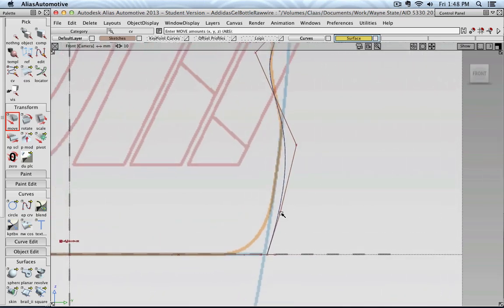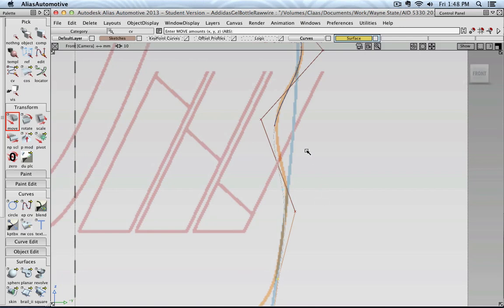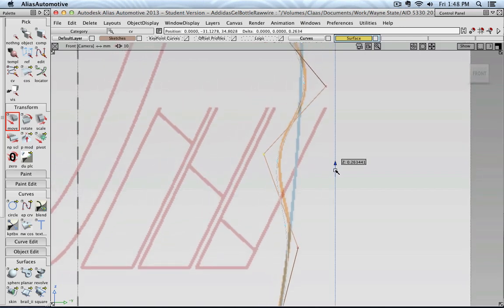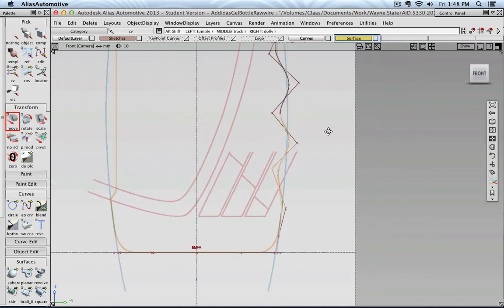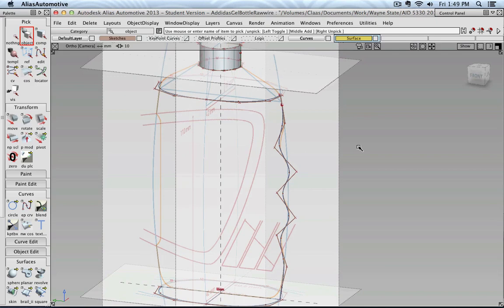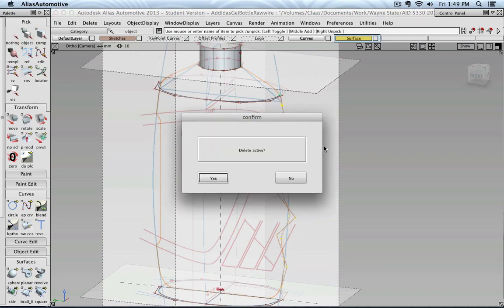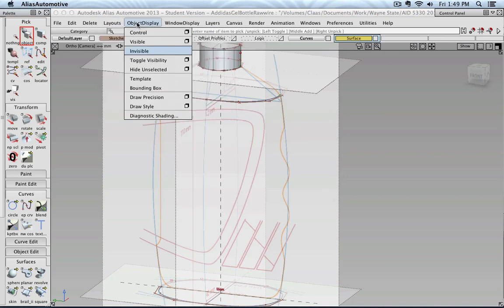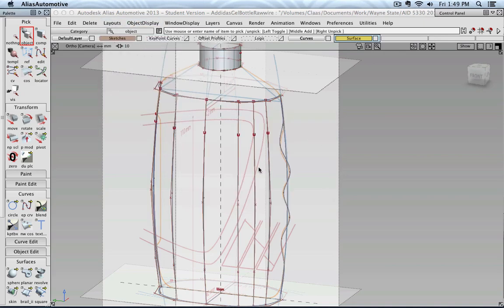And here I have to do the same. So I move it over onto the blue line and maybe a little bit to there. And we can still adjust that afterwards, thanks to the construction history. Okay, so that is the way I created the profile for the hand part. So let me show you the curves again. I deleted.